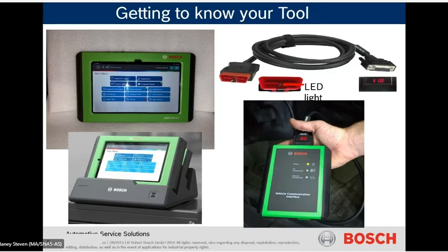There is no battery in the VCI. I get asked that question a lot. There's a capacitor in the VCI, and what it's for, you'll see when you take it away from power, the lights stay lit for maybe 30 seconds or so. That's really there so if you have it plugged into a car and you, for some reason, kicked it out of the diagnostic connector, or it falls out or something like that, you can pick it up and plug it back in and it would still be powered up, so you wouldn't have to do a rescan. But there is no battery, so I do get asked that a lot.